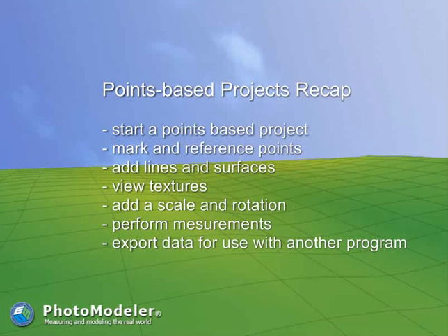This concludes the points-based introduction tutorial. We have learned how to start a points-based project, mark and reference points, add lines and surfaces, view textures, add a scale and rotation, perform measurements, and export the data for use with another program.